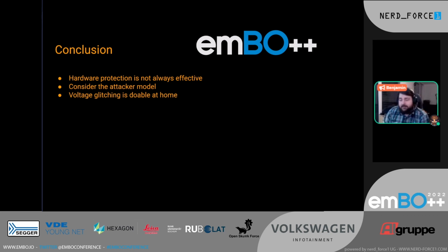Because in the end, it doesn't matter if it needs to brute force for a few days if you get your foot in the door, because you only need to do it once to actually grab your software, and then you can do the same trick we did last year. You have the software, you erase the chip, you flash back the software, but this time you do not enable debug protection, and you have a fully unprotected device.